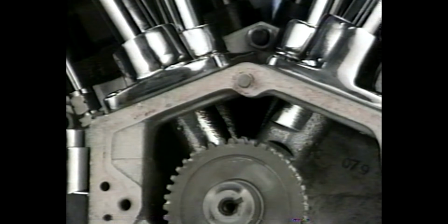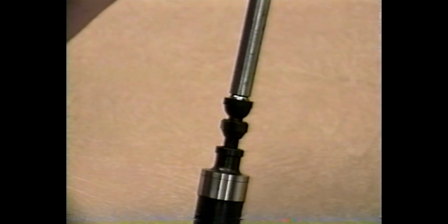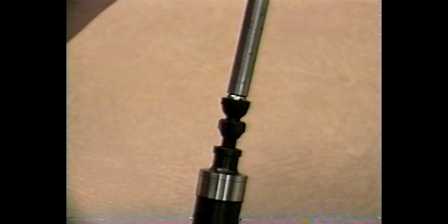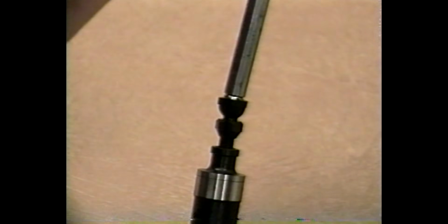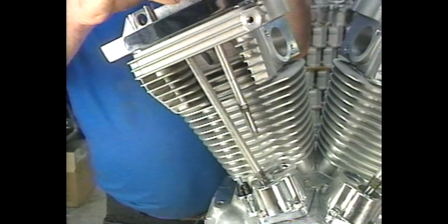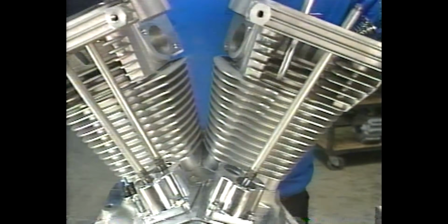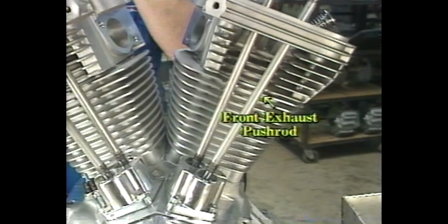But unfortunately, this is not possible using a single camshaft. The stress on our push rods increases the further off-center they are. The worst stresses act on the front exhaust push rod on any big twin engine. These stresses are greatly increased when design modifications are introduced that increase valve lifts or spring pressures.